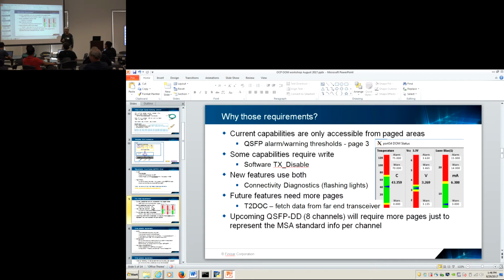Same device. So we would need a driver, and I don't know what interface an XFP has. If it's I2C and paged, isn't that the one we talked about online? XFP, I believe, is I2C and paged. So we need to test it, but I think it should work. We need to support customers that are using OLM today, so we need to make a driver that will support this going forward.